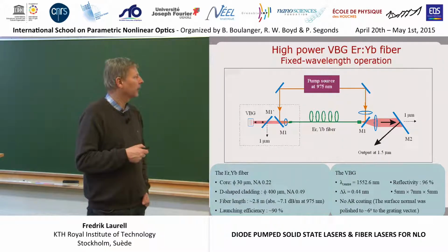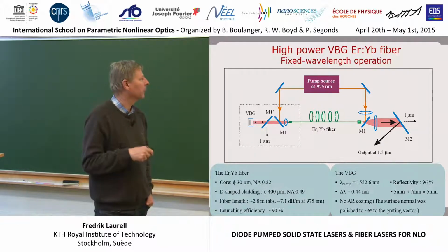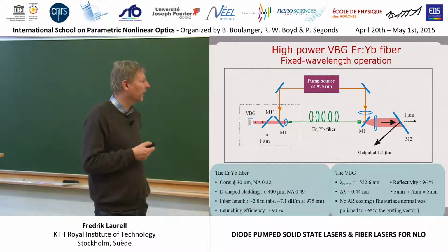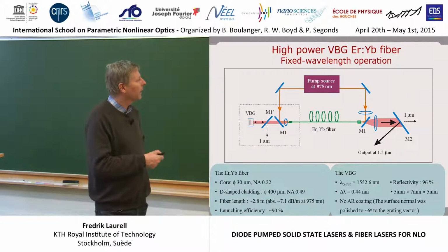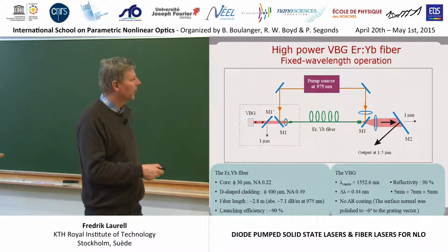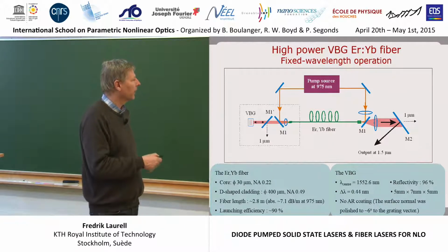Okay, so the next thing we thought that we need to learn to do high power lasers. So we started to collaborate with Andy Clarkson in Southampton, and then we took first the erbium-ytterbium laser, and it has to be pumped quite hard. So pump it from the two sides. We used the cleaved end face on one side and the VBG on the other side. So we had the output coming here, and to avoid any problem with the ytterbium, we let the 1 micron light out there.